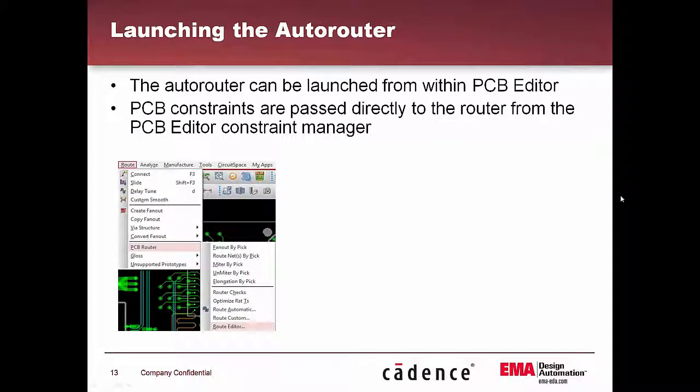Then the Autorouter can be launched directly within the PCB editor. You could also run it standalone if you want. There's a number of different modes that you can run it in here. So you can run it in what they call route automatic, which will give you a simple little GUI, and you can go in and select the number of routing passes and things like that. There's also a route custom, which lets the router try to figure out the board and come up with the result for you.